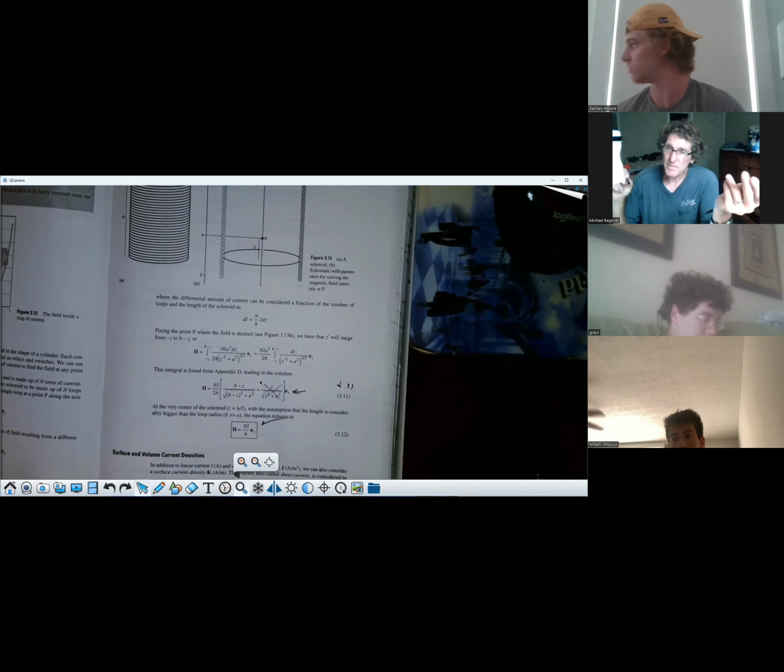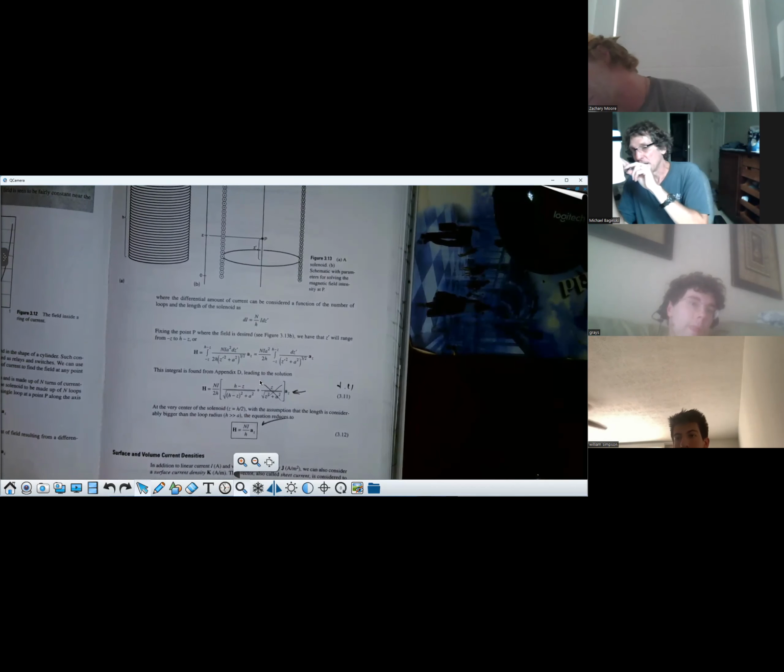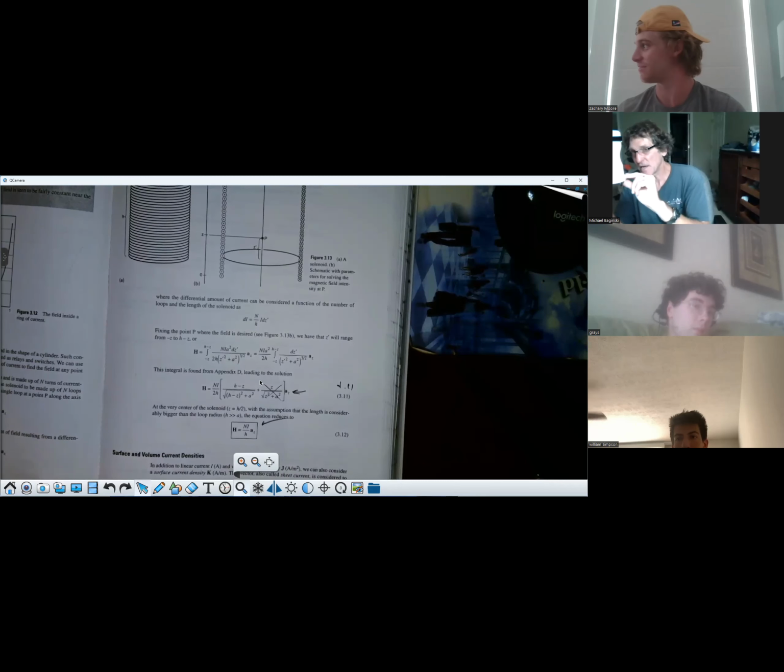You know what magnets are, right? Yeah. All right, well, now here's the deal. With a coil gun, you energize the coil and let the ferrite piece of material, magnet, go, and it's going to accelerate towards the center, and then you quench the current, so the magnetic field's going to 0 before it hits the center, and it just launches the thing.